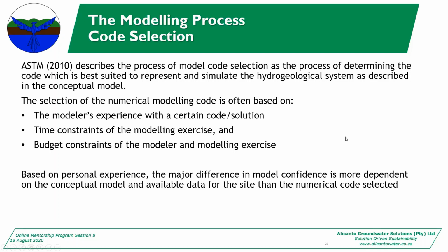Yeah, based on my experience, the major difference in your model confidence is more dependent on the conceptual model and the available data than the code selected. Yeah, if you've conceptualized your system properly and you've interpreted your data properly, your modeling code makes very little difference to the actual outcomes. If you can understand your system and present it properly, the model only adds to your initial conclusions. If you have a bad conceptual model, it doesn't matter what model you use, it's going to be bad.